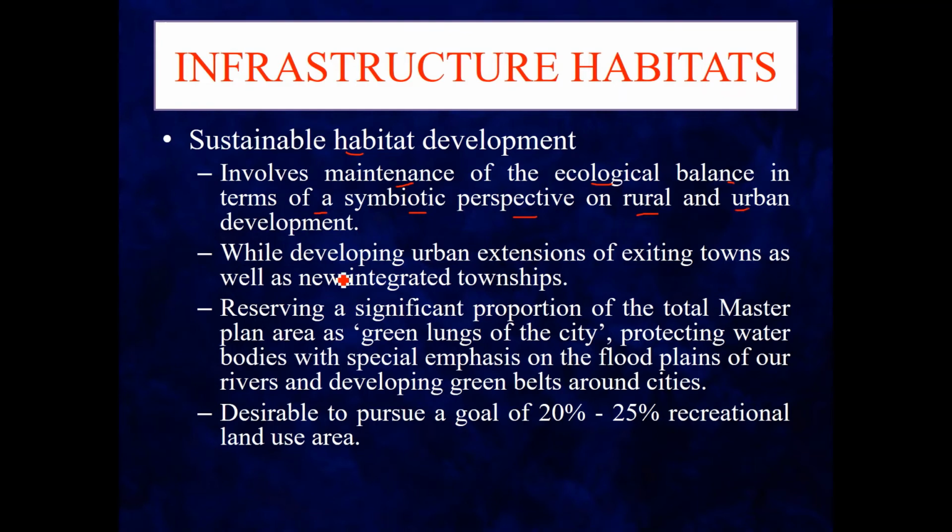urban development. One, developing urban extension of existing towns as well as new integrated townships, reserving a significant proportion of the total master plan area as the green lungs of the city, protecting water bodies with special emphasis on the floodplains of our rivers and developing a green belt around the city. Desirable to pursue a goal of 20-25% recreational land use area.